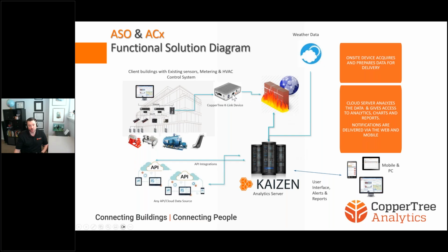So what we're saying is we are still reading data through the same device. If we have an FDD implementation in place and we want to do supervisory automation, in our current application we add a second device. That may not stay that way forever, but for the time being, while the industry is getting used to this shift from read-only to dynamic optimization, we found it was better to add a second device which will handle the two-way interaction with the building automation system. For various reasons, one of them is that we compartmentalize those. So we have the read device and then the two-way interaction device. And notice I'm not saying the write device because we're not always writing.